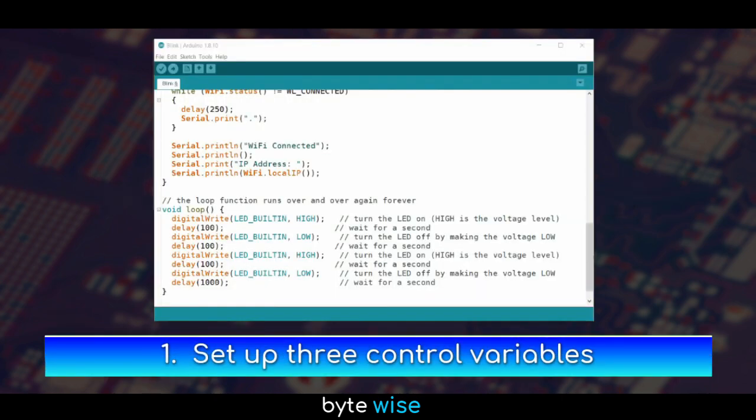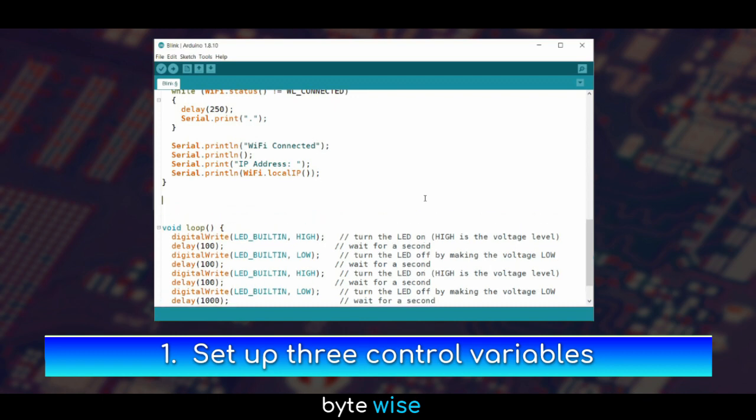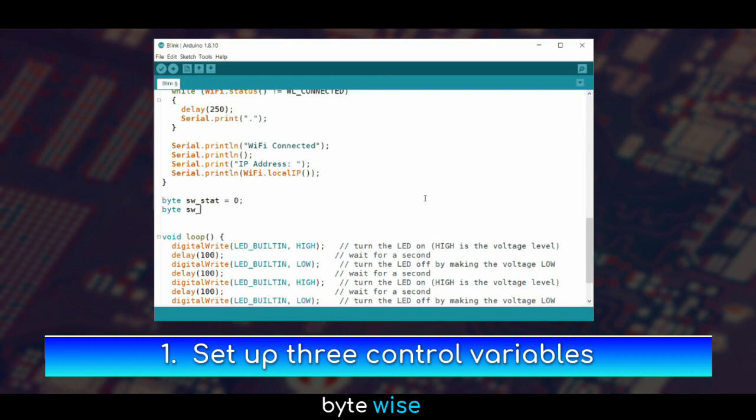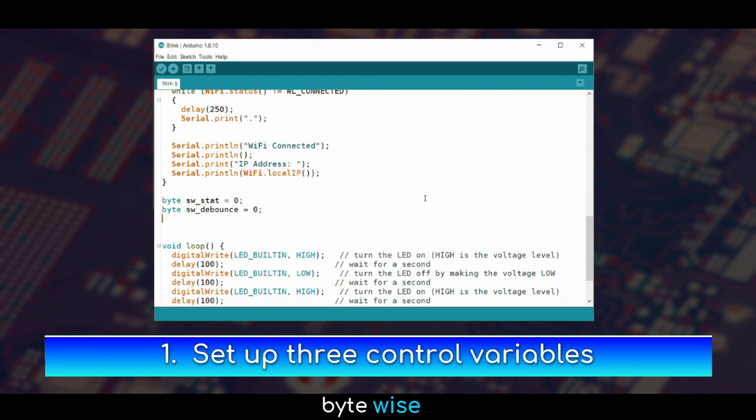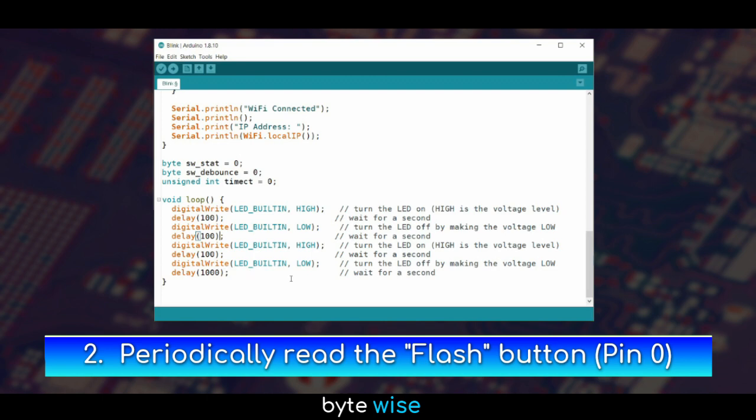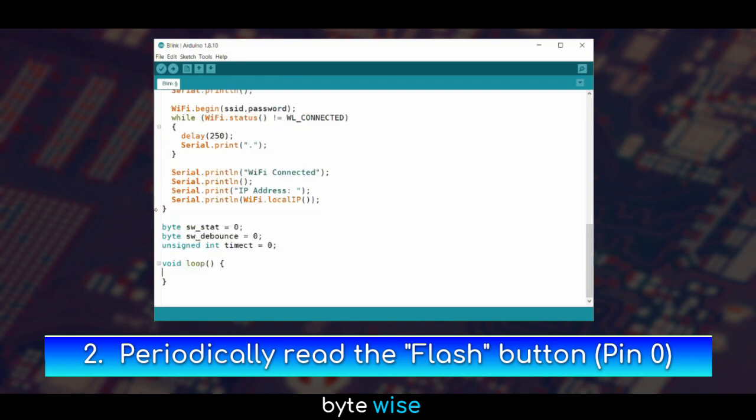Although the ESP01 only claims 1 dedicated input-output pin, in fact TX, RX and GPIO0 can all be used for extra input-output tasks. For this project, GPIO0 will be used for manual input. This is useful because we already have a button for it, although there is a potential issue that if both buttons are made available for the end user, it will be possible for them to put the project into flash mode. The first 2 variables here will track the status of the GPIO0 button.